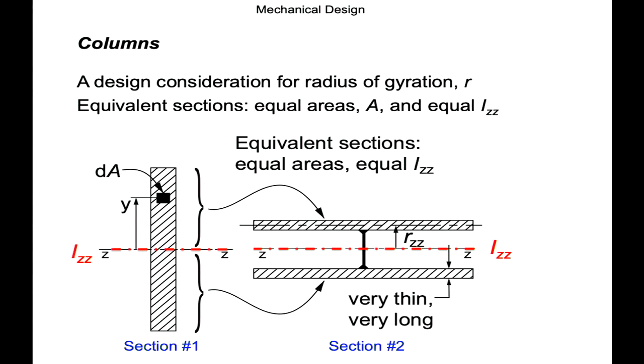and in this case, it's been designed in such a way that IZZ for 1 corresponds to IZZ for 2. You have to do a lot of playing around to make sure that the material out here, the extreme fibre, is equivalent to all the material performance of the extreme fibres of these column top and bottom.